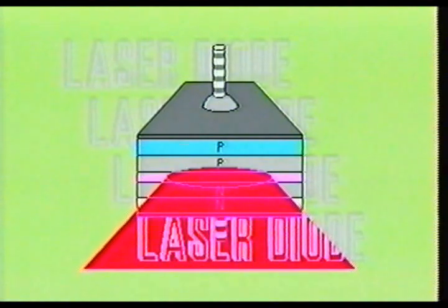The photon energy begins to reflect back and forth from one end of the waveguide to the other. As the photons collide with other excited atoms, more photons are created. The photons continue this back and forth cycle until the photon energy is amplified into a coherent beam of energy. Once the photons are sufficient to overcome any losses due to absorption and scattering, the laser beam will exit the front facet of the laser device. The beam of light emerging from the front of the laser device will form a vertical ellipse.